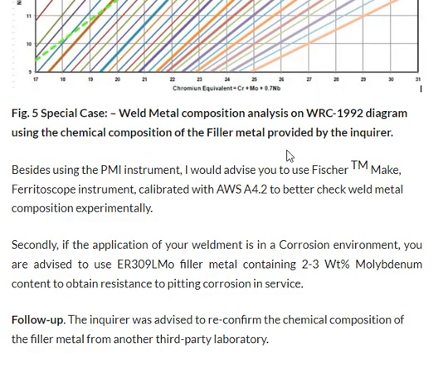At the end of this video episode, my recommendation is to use a proper filler metal and to check the chemistry of the filler metal either with the EQT or by the supplier's test certificates with the ASME Section II Part C consumable certification, and to use a low heat input as much as possible.